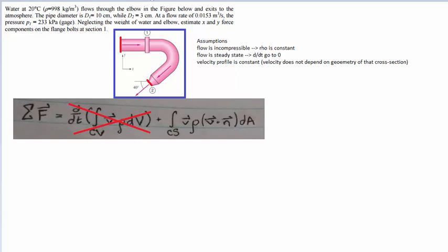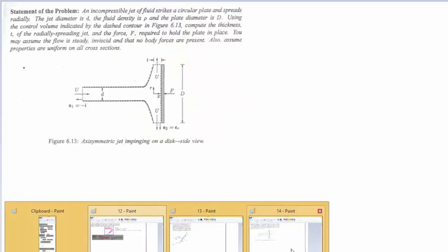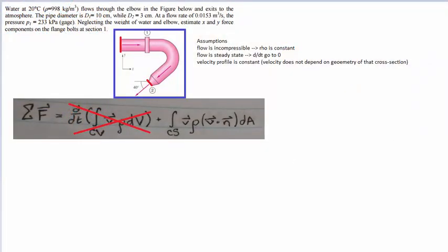We don't know the direction of these internal forces, and we don't know the magnitude, but typically, when we have these sorts of forces, we just assume that they are positive. The point I'm going to make is that right now we should assume that everything is positive, and since we're doing a multi-dimensional problem, the vectors will actually tell us the signs later.